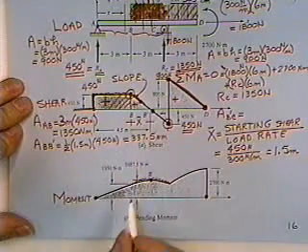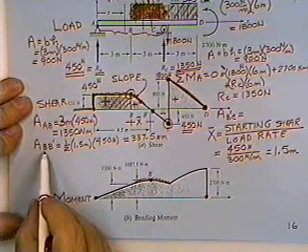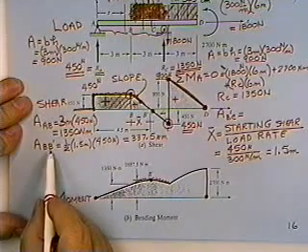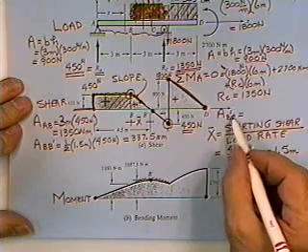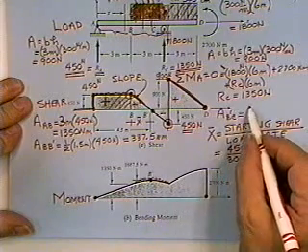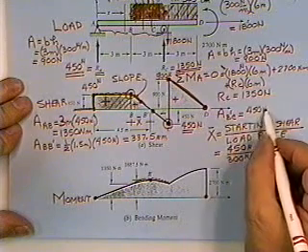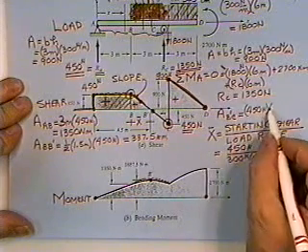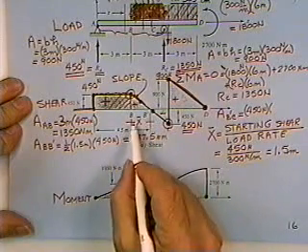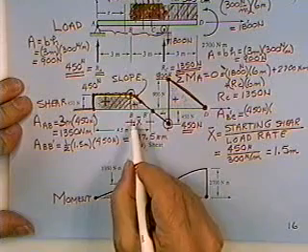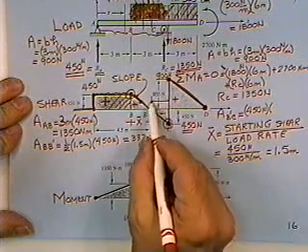All right. So now I've got justification for calculating the area BB prime. Now I'm going to calculate the area for B prime C. It is 450 newtons tall. It has a base. Well, if this is 1.5 right across here, out of 3 meters total, this is also 1.5 across here.